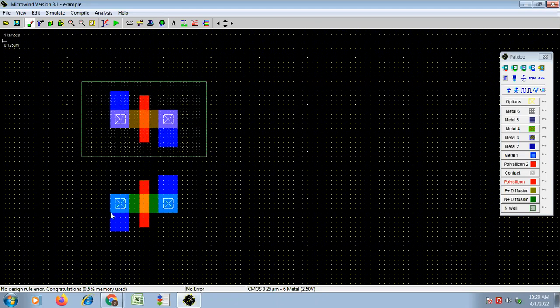Okay, similar is the case with this NMOS also. This red polysilicon is a gate. The left side part you can treat as a source or drain, or vice versa. Now all of you are aware of the CMOS circuit. The source of PMOS is connected to VDD. So we will assume that this left side part is a source terminal, so we will just extend this metal. And now from this, here is a VDD supply, so we will choose this VDD supply and connect here.